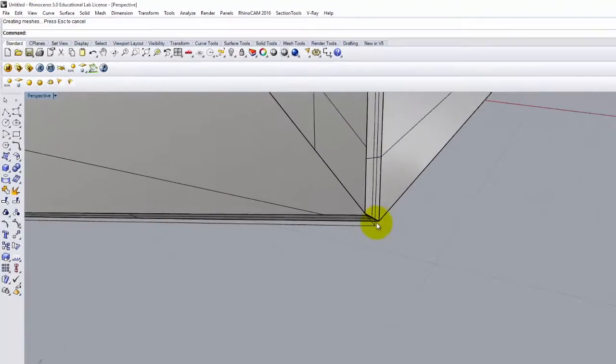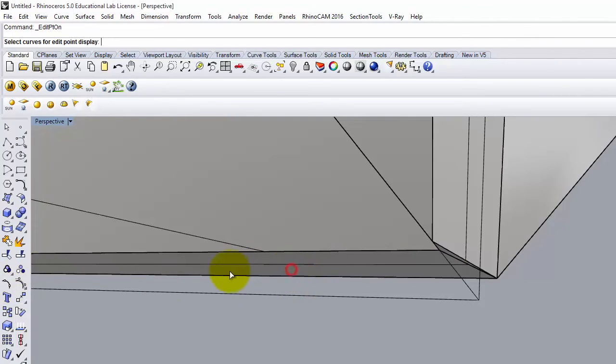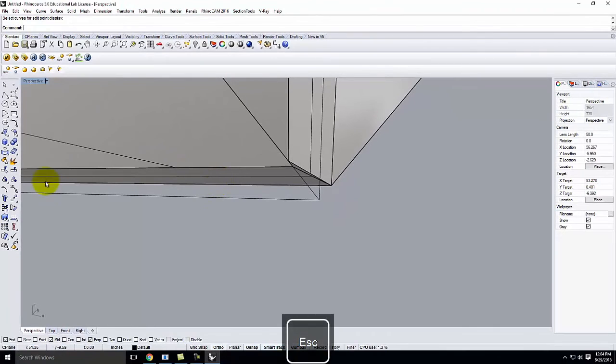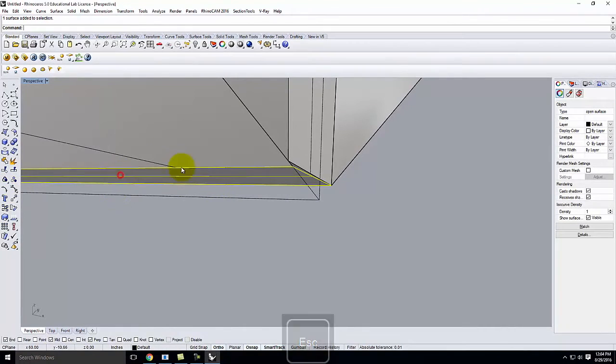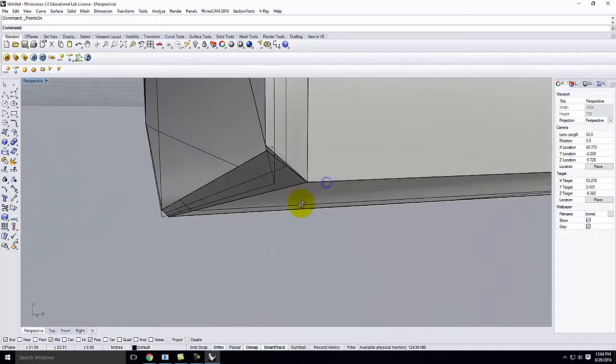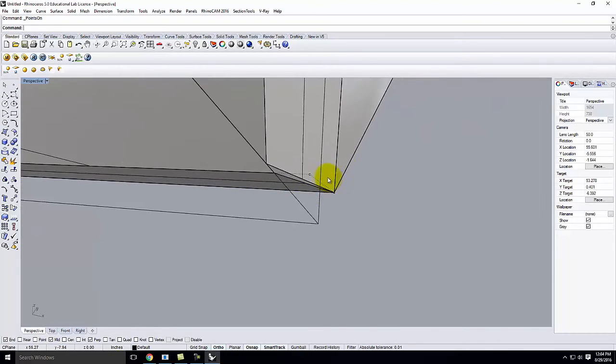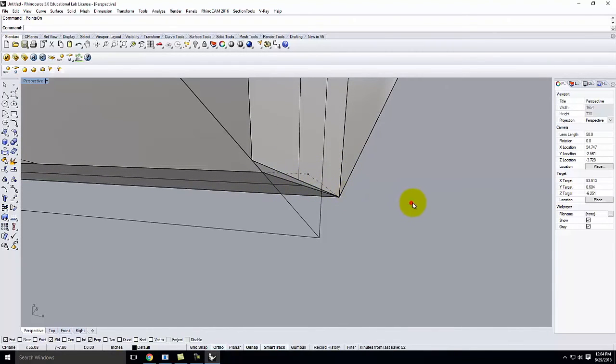The alternative to that is I can actually modify this surface as a whole. Okay, and I can do that by turning on something called edit points. And if you look over here, there's kind of a curve with some dots on it. If I click on that button, right? No, excuse me, it might be the one next to it. Let's look, curves. Yeah, that's for curves. I have to do the one next to it. It's points on. If I take that and I click on the one next to it, points on, or I type points on, you see that I actually get control points for the corners of my surface. Right? There's a slight problem with this surface because it's already been trimmed once. So it's showing me what the surface was before it was trimmed. So I'm going to do two things.